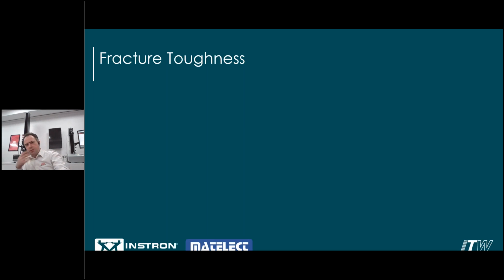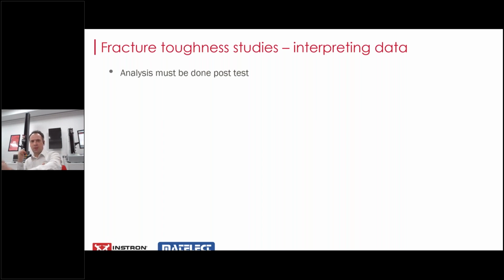So the next thing is if we talk about fracture toughness. Now, with a very brittle fracture toughness, measuring crack extension is not usually relevant. There are certain tests which are actually similar to the large plate test I just mentioned, where you do, but the vast majority of tests you will have heard of, ASTM E399, the K1C test. We are assuming a single point and a sudden catastrophic failure.